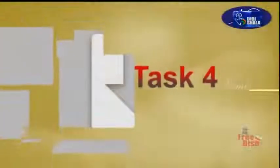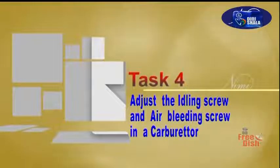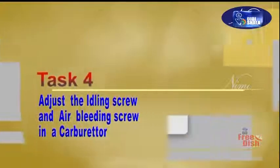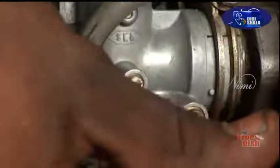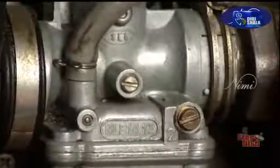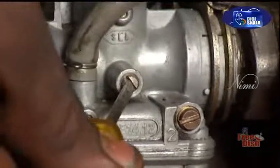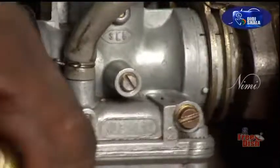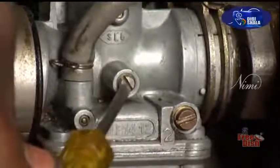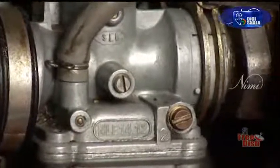Task 4. Adjust the idling screw and air bleeding screw in a carburetor. Adjust the idling screw to make sure that the engine rotates the crankshaft at 1500 RPM. Under cold conditions, set the idling at 1300 RPM, which will increase when the engine warms up.